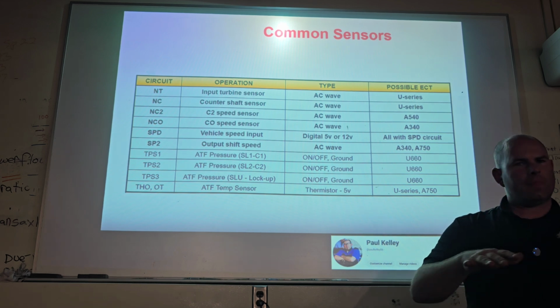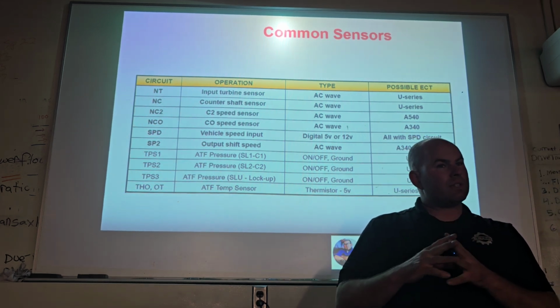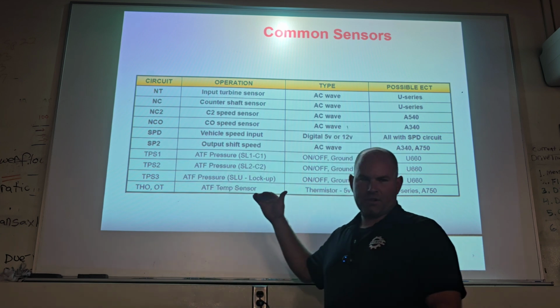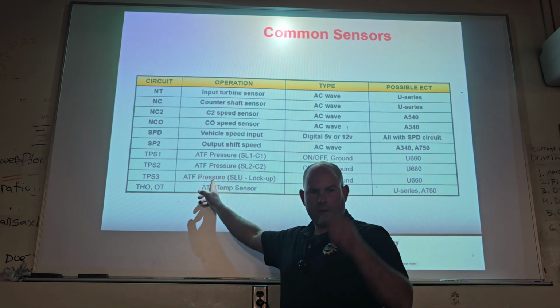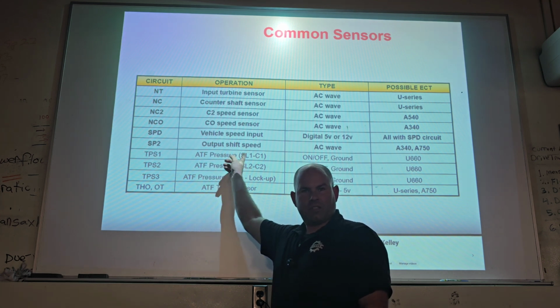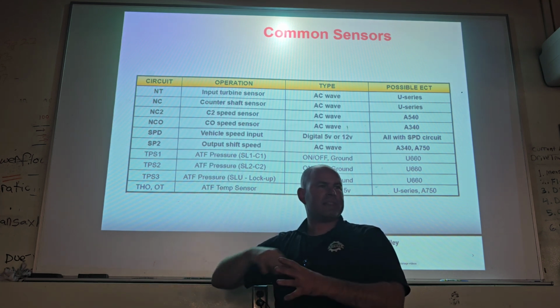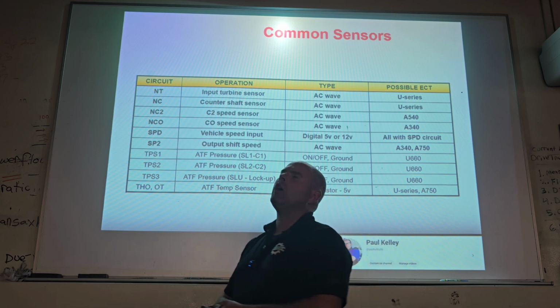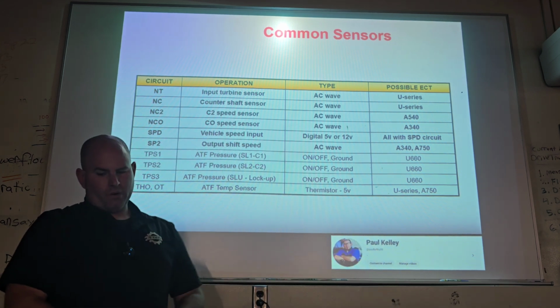The clutch. You don't think it's a leaking seal? You don't think it's like a hydraulic leak? Because if it was, you wouldn't be getting 140 on this pressure sensor. See what I'm saying? See how much tighter the diagnosis is when you have the pressure sensor to verify it's getting full pressure and not leaking in the valve body or leaking at a piston seal? Amazing. But we don't have them for all of them.